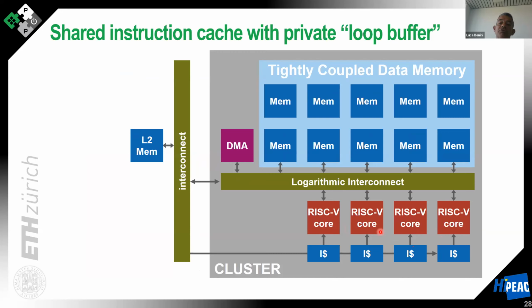And this is actually overhead. Each core will have to fetch a stream of instructions, and if they all go to a global memory to get the instructions, you will lose all your energy efficiency because of this huge instruction bandwidth that you have to provide from the memory to the many cores. And all the cores always fetch instructions every clock cycle. So the traffic to that instruction memory is enormous.